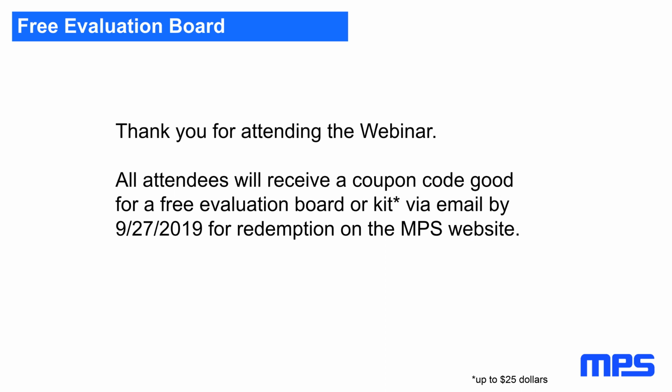Okay, the next question was revisiting one of the earlier slides to elaborate a little bit more, or just cover again the comment about, I think this was the input filter, the inductor followed by an electrolytic capacitor instead of a ceramic capacitor. Actually, this electrolytic capacitor is not doing much on the EMI side, because an electrolytic capacitor has several hundred milliohms ESR, but it typically damps audio resonances you get.